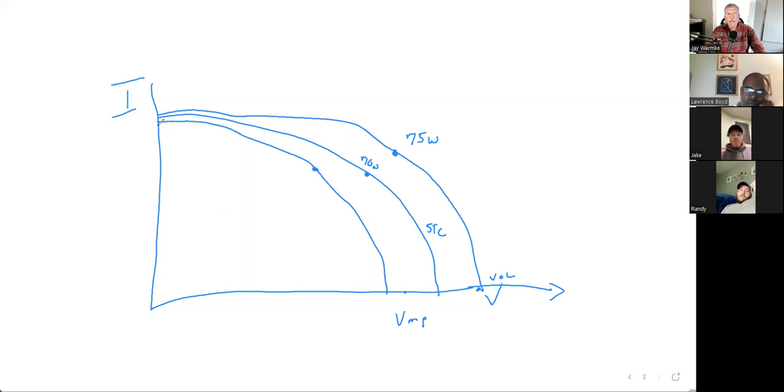Also, the other thing is amps. Let's say that it gets cloudy. Well, then my curve might go like this. You know, it got cloudy. This is at 1,000 watts per square meter. Well, what is it at 600 watts per square meter? The curve might look like that. So now my MPPT might have shifted over here. So it's always adjusting, always adjusting.